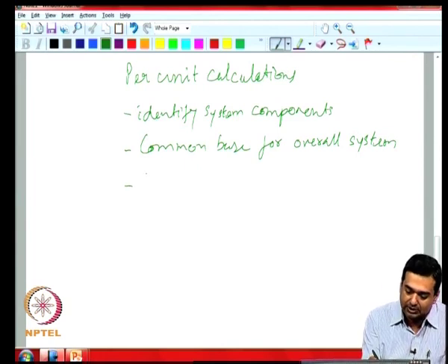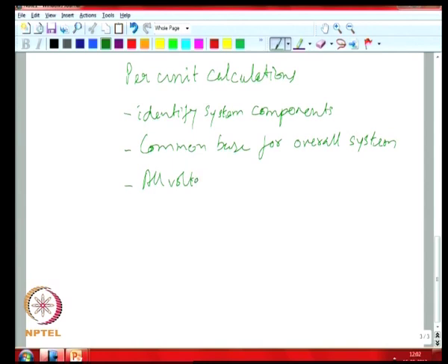So, all your voltage levels and your transformers are transparent, and you bring in all the impedances for the different locations, from different voltage levels, to a consistent per unitized basis. Okay. I mean, you will get a better feel for it when we look at an actual example where we can go through and do what calculations we would need to do.